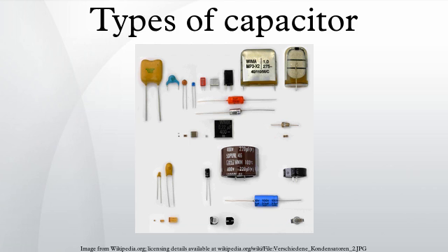The permittivity and the dielectric thickness are the determining parameters for capacitors. Ease of processing is also crucial. Thin, mechanically flexible sheets can be wrapped or stacked easily, yielding large designs with high capacitance values. Razor-thin metallized sintered ceramic layers covered with metallized electrodes, however, offer the best conditions for the miniaturization of circuits with SMD styles. A short view at the figures in the table above gives the explanation for some simple facts.